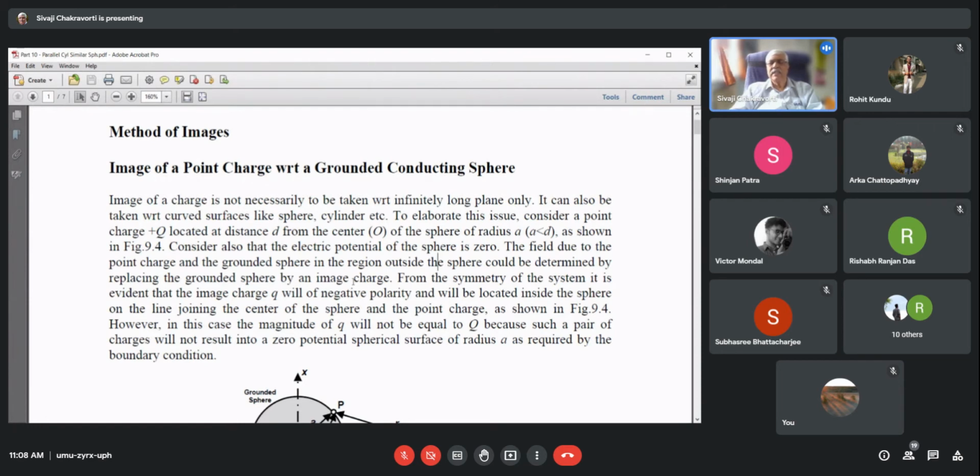Can you give an idea? A switch will operate at, let's say, 50 kV or 33 kV, and it should operate in 1 microsecond. What type of switch can I give? You cannot use circuit breakers and others. They operate in maximum half cycle, which is about 10 milliseconds.